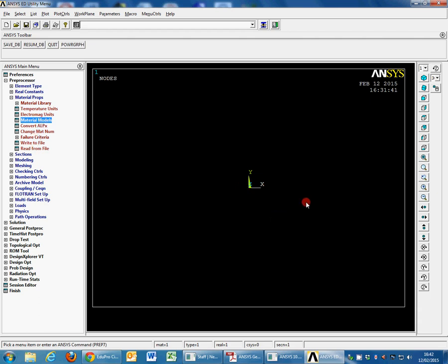So in this instance, because each beam is 4 meters long, I'm going to choose every half a meter to have a node. So that means I need 8 elements every 0.5 of a meter long in each of the spans. So 8 with 3 spans, 3 x 8 is 24 elements. So if I've got 24 elements, that means I need one more node than I have elements, because the elements connect between nodes. Okay? So that's my philosophy here relative to the model that we're inputting.